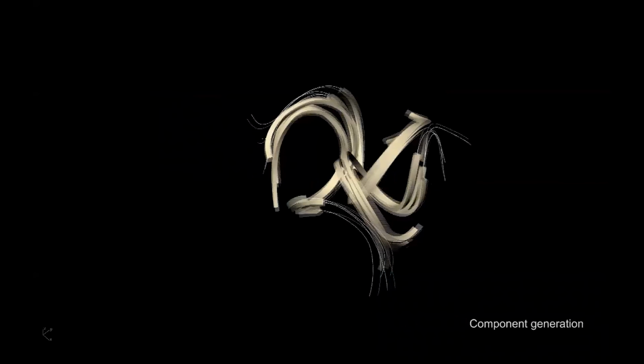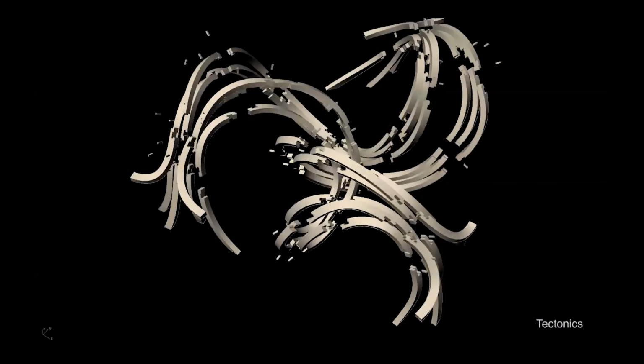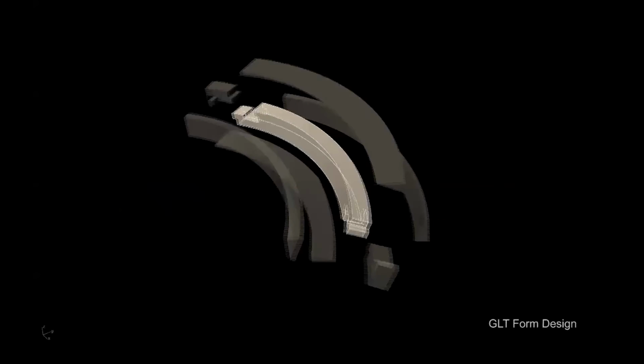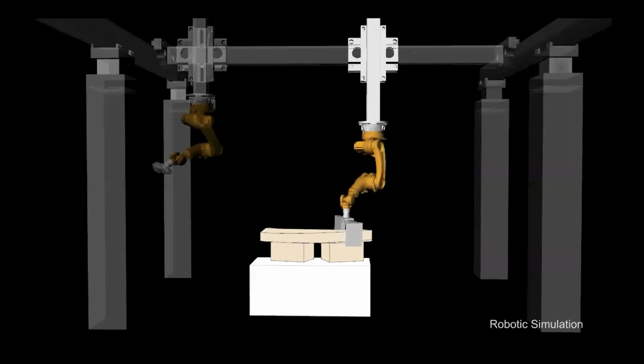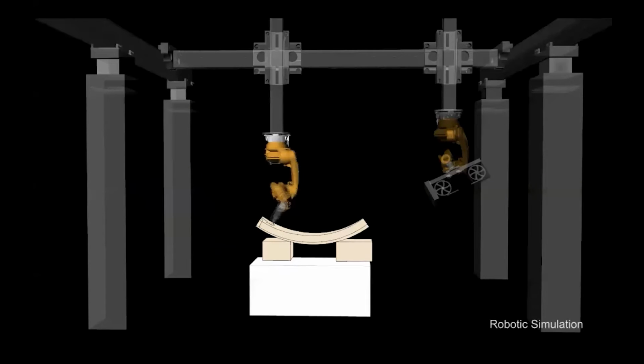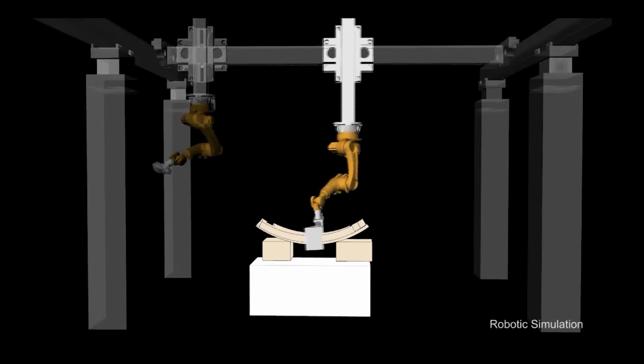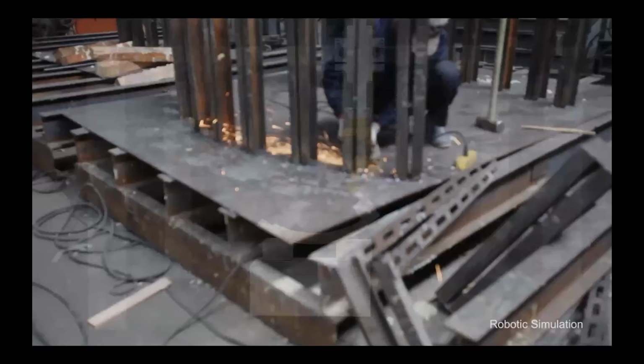The first is geometry form finding. So normally the timber is straight, right? We tried to challenge whether the timber could be curved. So we developed the geometry and defined them component by component. And the most difficult part is how to fabricate them. So we implemented laminated wood and two robots, like two hands of the human body. One is milling, one is sawing.